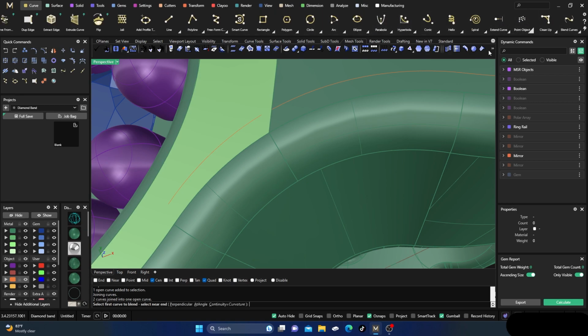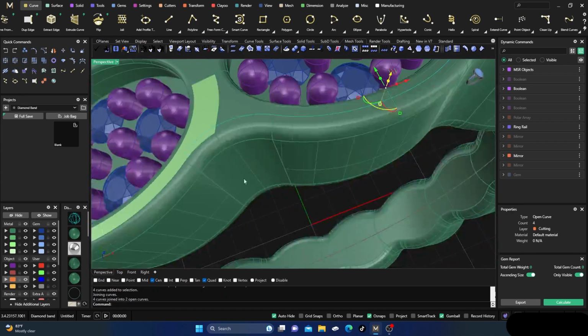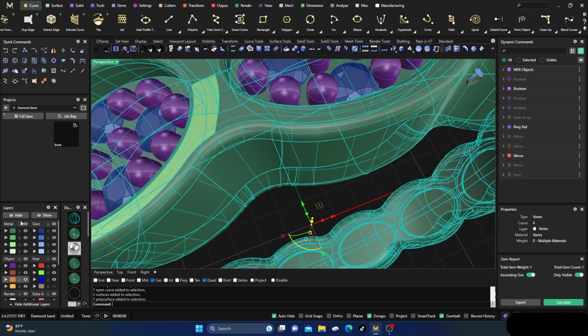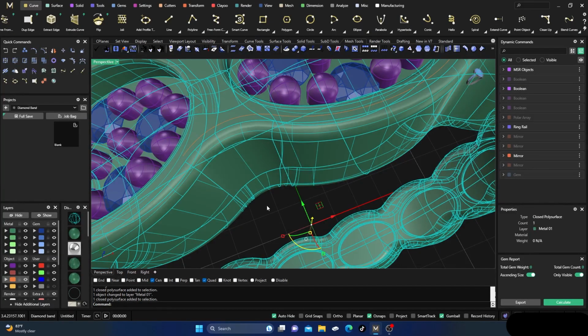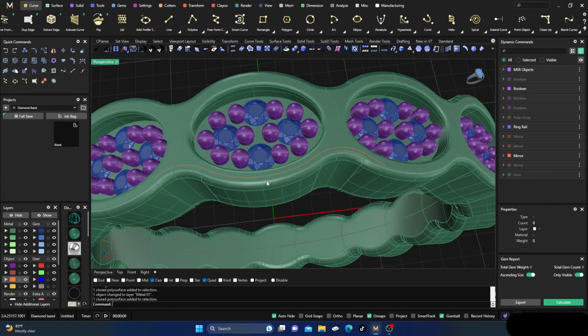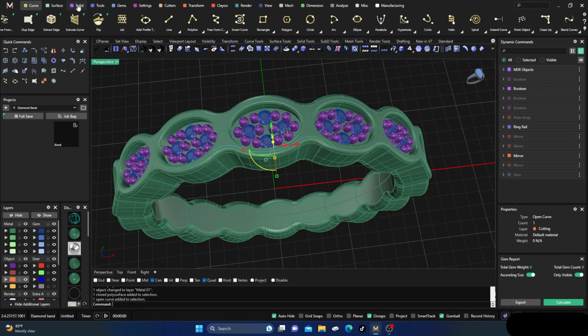So let's go in here and do a blend from that curve there to that curve there, right? And let's take all of this and join it together, okay? So we have that. We're cheating a little, but hey, you know. So we'll grab all this, and we'll join that back together. And that's kind of bright, so close polysurface. All right. So now let's see if we can line this up where we do not have to go through there and do the whole surface.